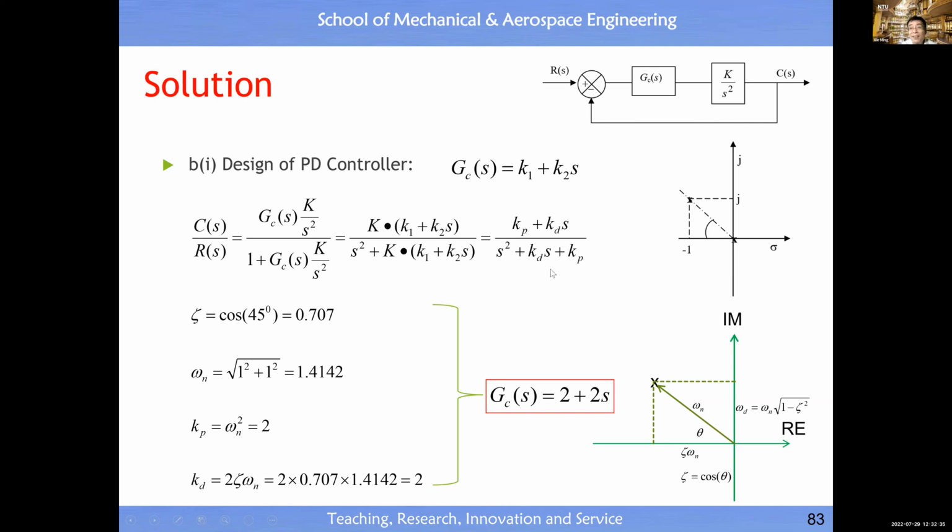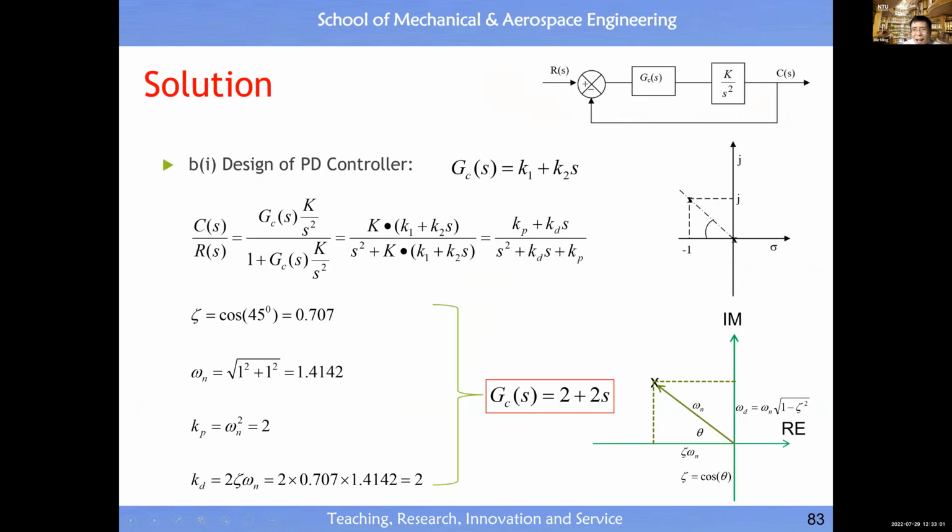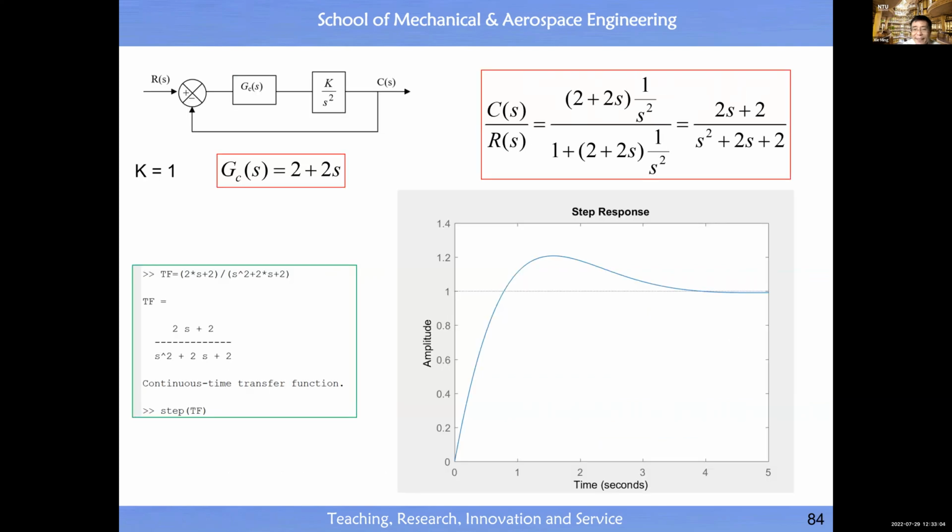So this is design method 2. All right. So we follow design method 2. Actually, it's a combination of design methods 2 and 3, because 3 uses a PD controller. 2 uses the standard transfer function of a second order dynamic system. So this is a hybrid design method, all right? Then you can easily calculate what is Kp, what is Kd, all right? Then you can use MATLAB to verify how good the control system is. You see, initially oscillation, after design it is very nice, all right? And response time, pay attention here, more or less 3.5 seconds, all right?